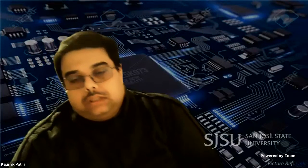I'm not sure about this, but I think when you have the register file and you don't put in all of the inputs at the beginning of your initial block, like the write address, then the output will not be high Z, it will be X, because you don't know what the write address is, and it's a combinational circuit. So if you don't know one of the inputs, then the outputs can't really be known. Oh, okay. I got it. I think that's what he was saying.